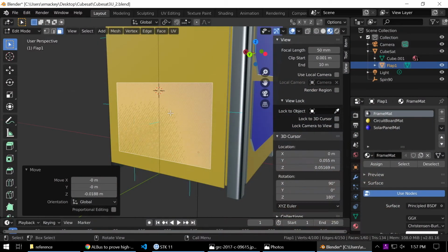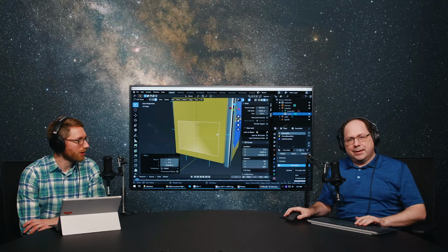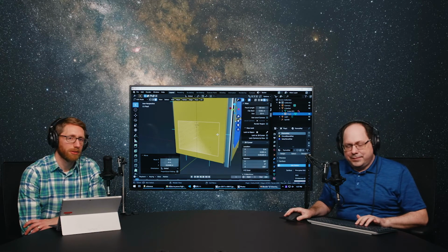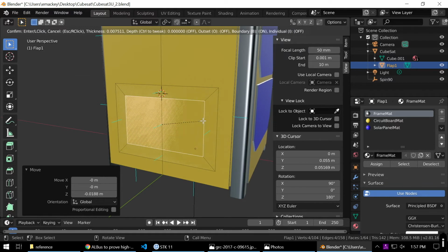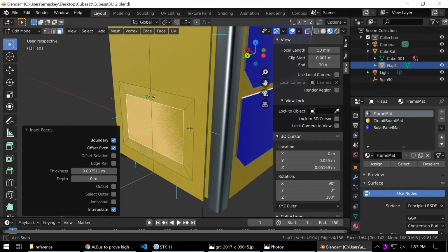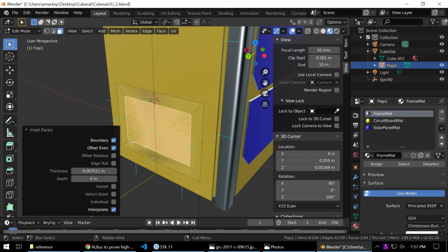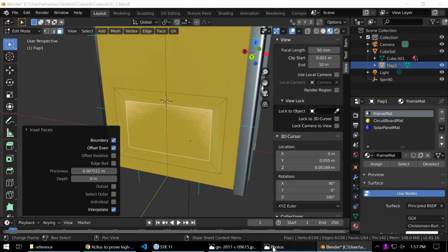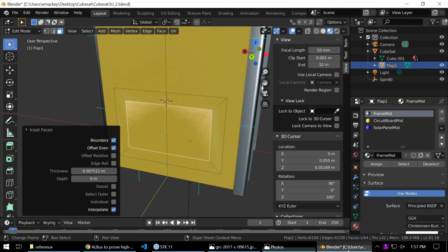For the panels, we extruded those cells. For the cells, we extruded them out. Would we do that again here and delete a backface, or? I was thinking of something different. I'm going to use a different function called inset. So I hit the letter I, and I'm going to make an inset. And it makes another panel inside of this one, but it does not produce a backface. So it's still 2-dimensional and it's still Z-fighting. But it made the right sort of shape of what I think I'm seeing in this image.